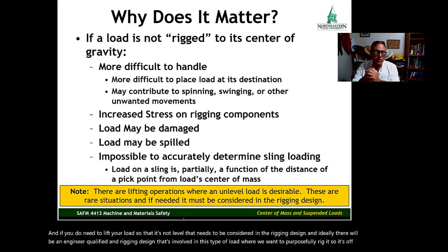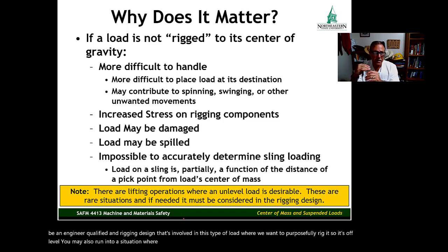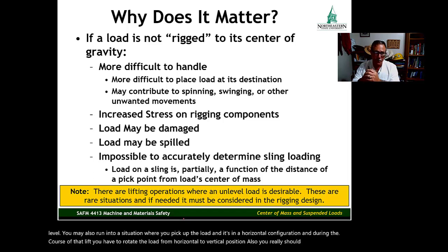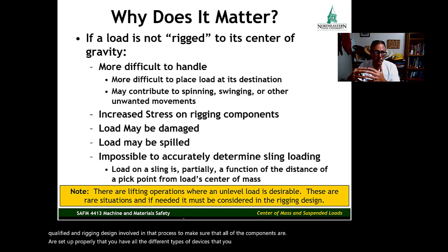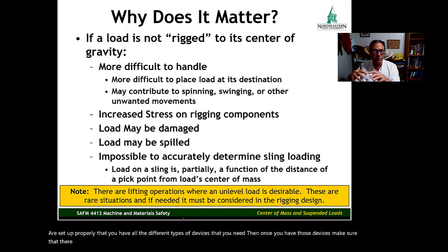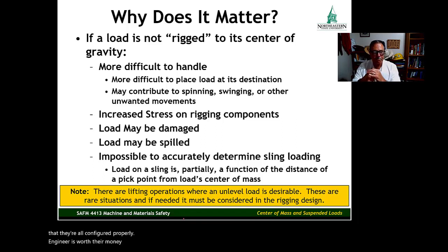You may also run into a situation where you pick up the load and it's in a horizontal configuration, and during the course of that lift, you have to rotate the load from a horizontal to a vertical position. Also, you really should have an engineer qualified in rigging design involved in that process to make sure that all of the components are set up properly, that you have all the different types of devices that you need. And once you have those devices, make sure that they're all configured properly. Engineers are worth their money in situations like that.